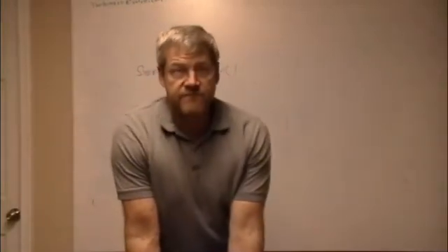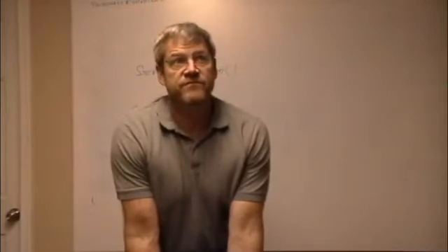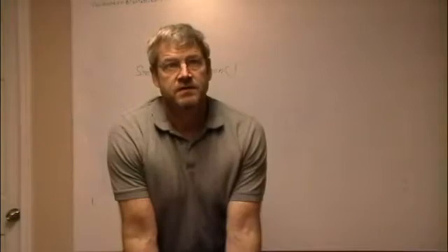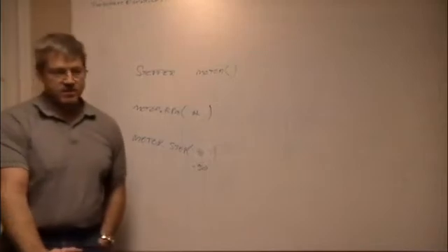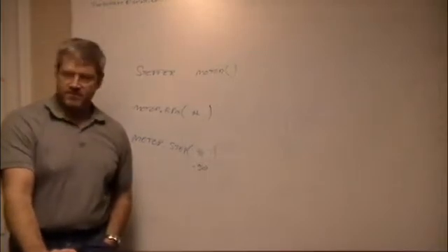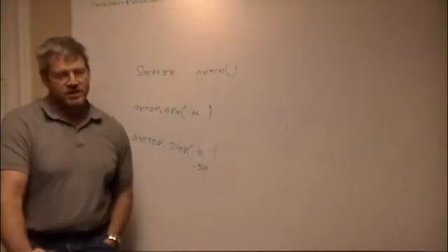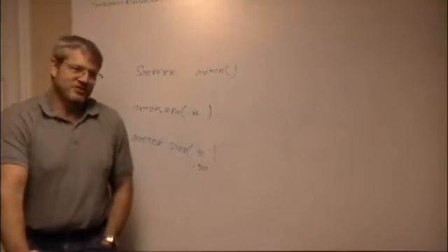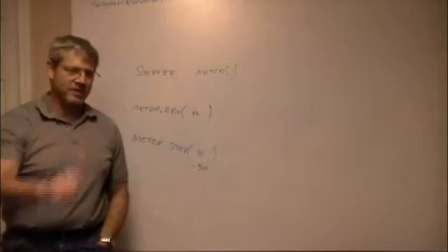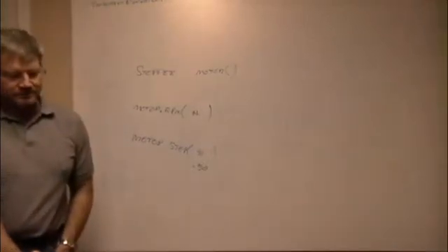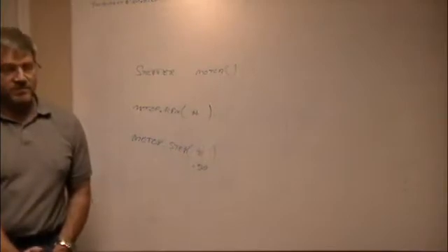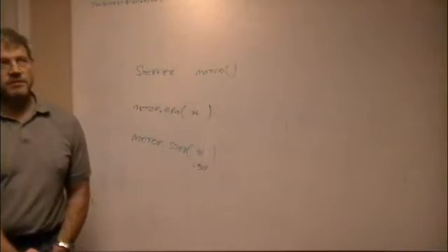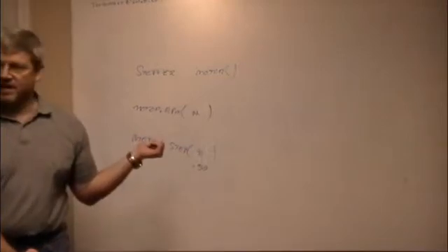I found that the fastest that I could turn the motor was about 17 RPM, because it's so many steps. It's a 64 to 1 gear reduction. You've got to go 2,000 steps to get one turn out of it. The minimum speed I could go was about 1.8 RPM.